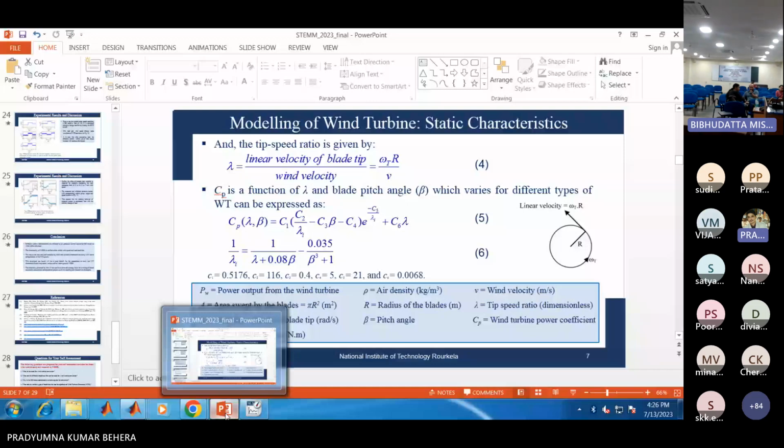See, I am only talking about the dual loop control strategy. In this, we have two control loops. The outer loop will regulate the output voltage of the converter, and the inner loop will regulate the current of the converter. Okay.